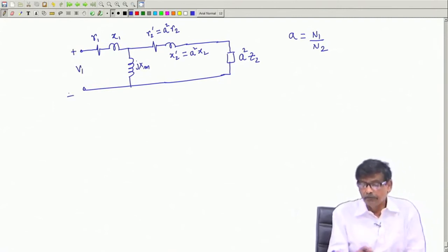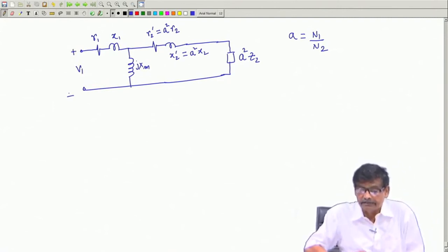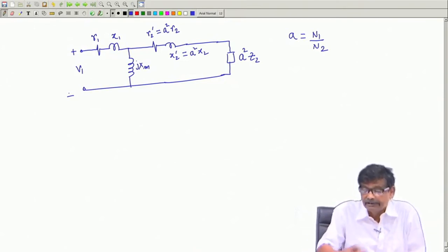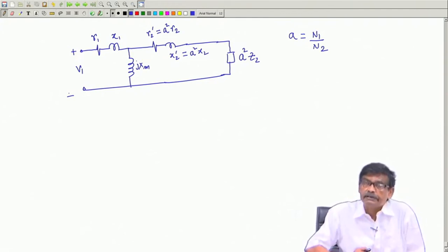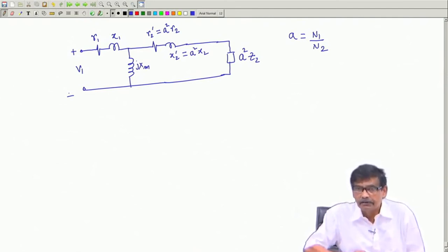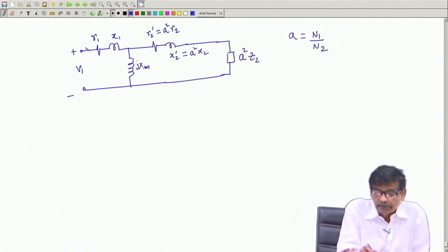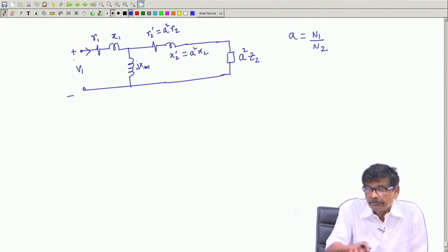So, it is almost the correct equivalent circuit of a practical transformer, but here in this equivalent circuit, what elements should we now add which will represent the core loss? Core loss means heating of the core. Heating of the core will take place because of eddy current loss and because of hysteresis loss. This is the only source of power which pumps the power into the system.